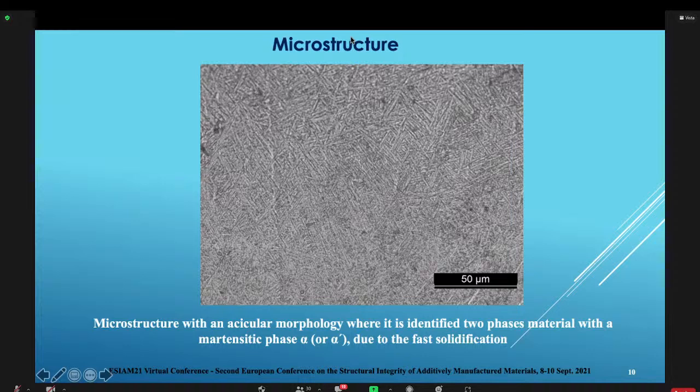Are there any other questions from the floor? Okay, well, since we still have some time, I have another question, if I may. You reported that you didn't really observe significant difference in closure effects. In previous work that we've done on laser powder bed fusion Ti-64, we noticed significant closure behavior at near threshold fatigue crack growth rates. I'm not sure if you've gone that low, but I was curious if you measured at near threshold fatigue crack growth rates?